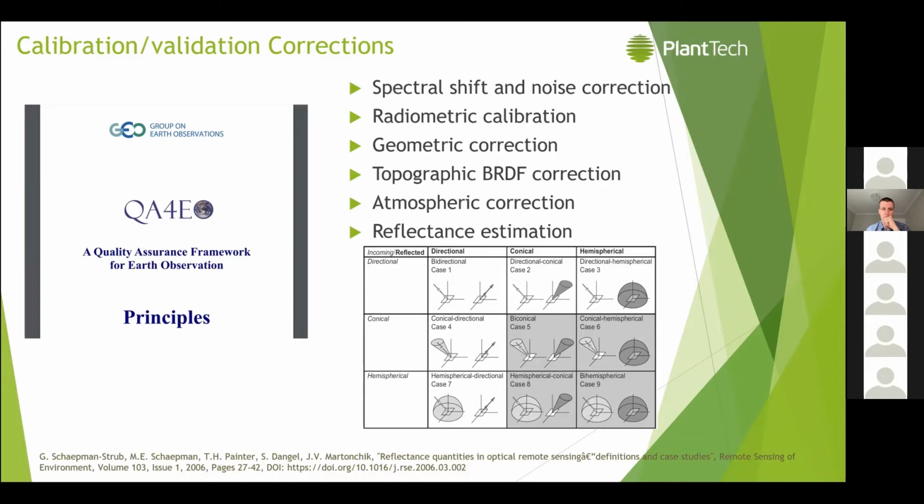In order to obtain a high quality reflectance product, we need to implement a series of corrections on the raw data. The spectral and radiometric calibration is usually performed under lab conditions. However, the instrument performance might change after installation in the aircraft, because of the aging of the optics and electronic components, temperature, and misalignment due to mechanical vibration.